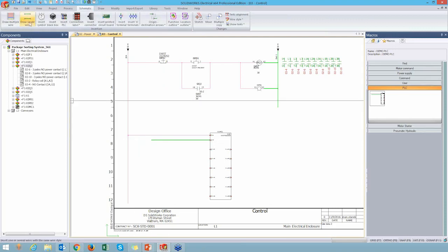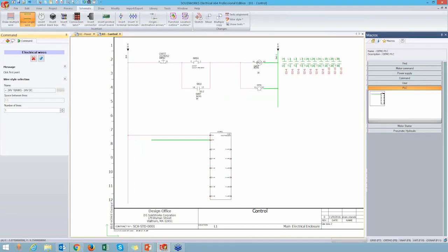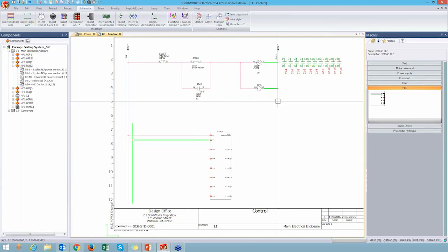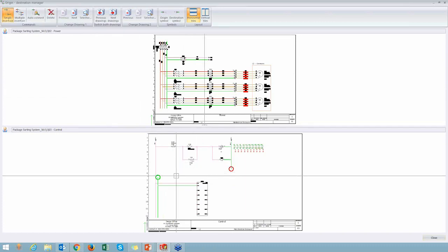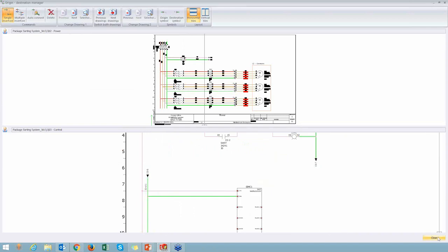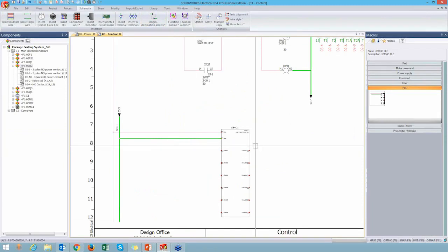All right, let's attach the ground here. And when I draw this, I want to just give it a little leg to connect to my ground circuit up here. So again, let's use origin destination arrows so I don't have to draw a wire all the way across and down. It'll just make it a little bit cleaner. Now again, it's only finding the ground as an option to connect to, so it's protecting us from making an accidental wiring error in my schematics.